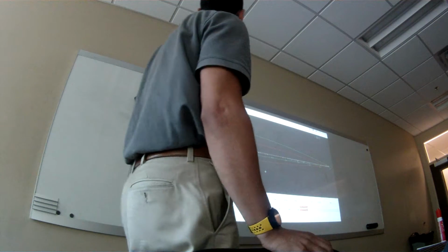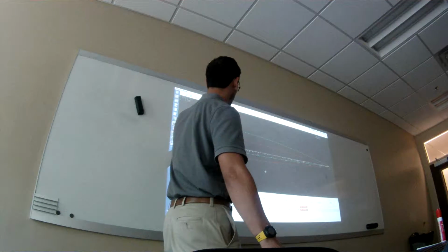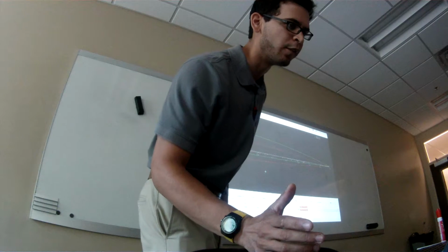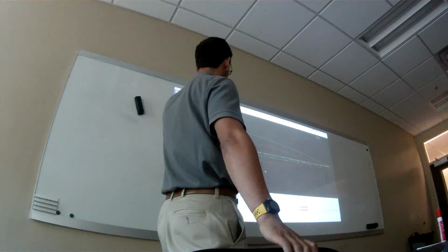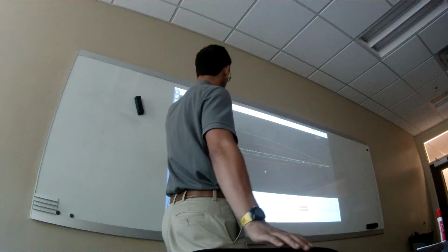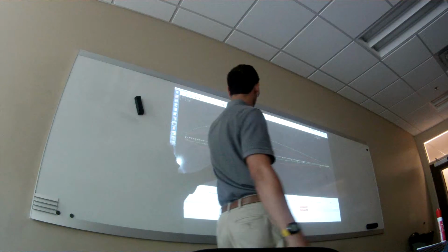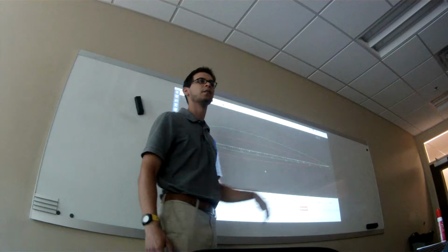So there you go. Look at that. There's a lot of camber, and it's thicker. Well, no, it's still a 4212, but this is a 0010. So this is 10% thickness. This is 12% thickness. But what do you notice about this wing? That looks kind of similar to that one, right? It's kind of flat on the bottom and then curved at the top, right?